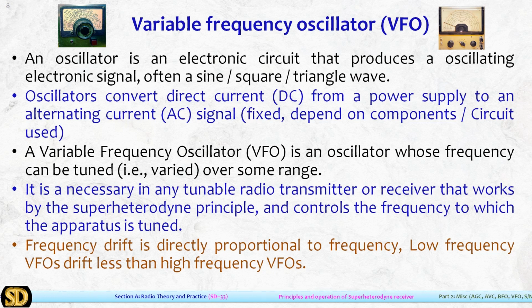Frequency drift, or variation, is directly proportional to the frequency used. Low frequency VFOs drift less than high frequency VFOs. If our VFO is designed for low frequency, drifting is less, but if it is designed for high frequency, then drifting is more, and stabilizing the frequency is also a question. So depending on our need, we can use different circuits for making a VFO.